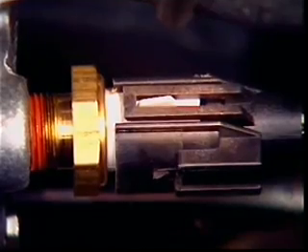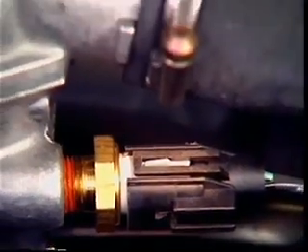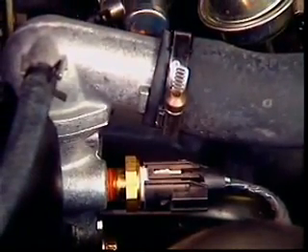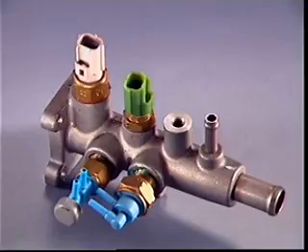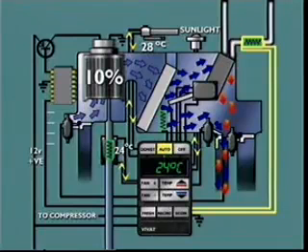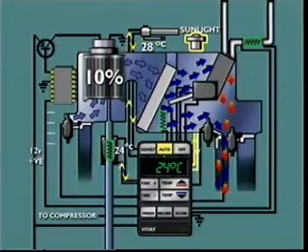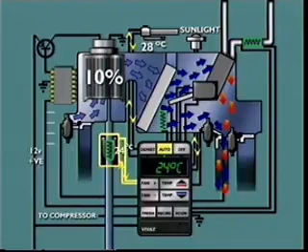The coolant temperature sensor for the engine management system signals to the climate control ECU the temperature of the coolant flowing in the heater core. Some climate control systems have a separate coolant temperature sensor, usually located near the engine management coolant sensor. The signal from the coolant temperature sensor is used in conjunction with the signals from the ambient air sensor, the sun load sensor, and the cabin air temperature sensor to control heater and fan operation.